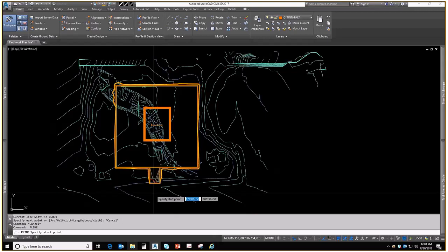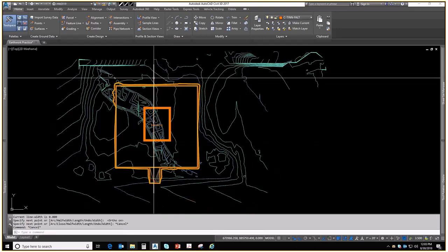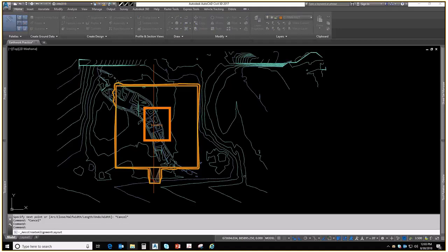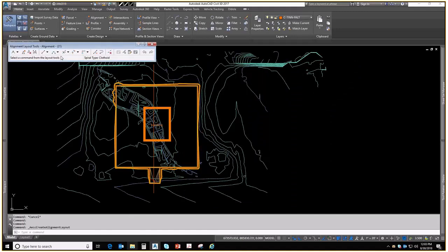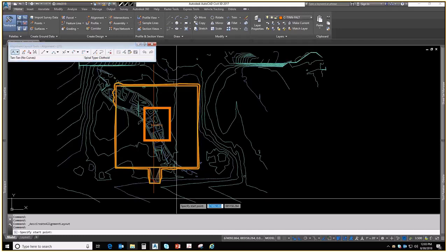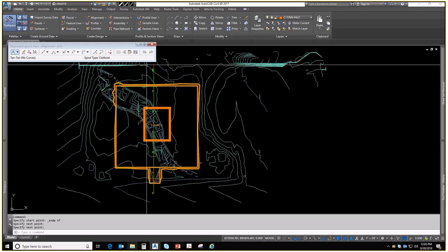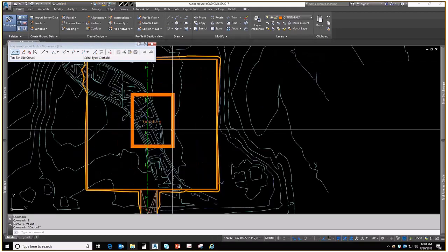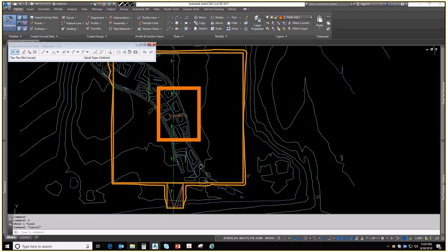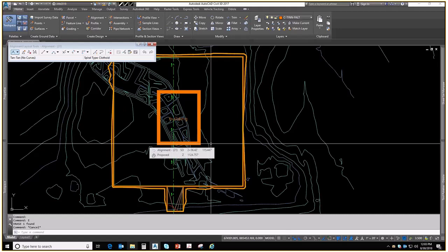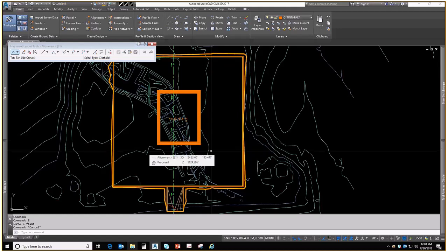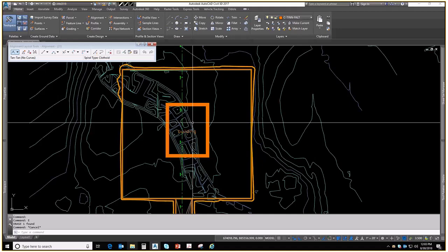As far as the logic of cutting sections, the first approach is let's do them every 100 feet or every 50 feet. But the refinement to that is when you're using average end area. The way the average end area system works, if you're not familiar, is you'll have 2 adjacent cross sections, and the computer will calculate the area in one section of cut or fill or both, and the area in the other section, and it will average those by 2 and multiply by the distance. So if you're not careful in how you cut your cross sections, you can actually have an inaccurate transition from one to another.